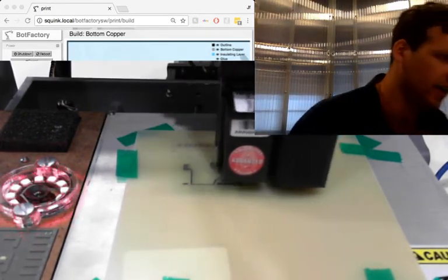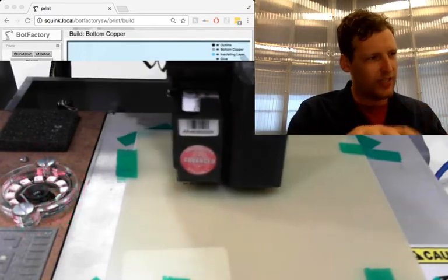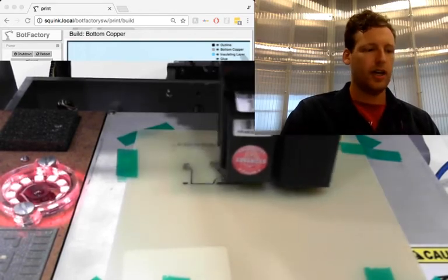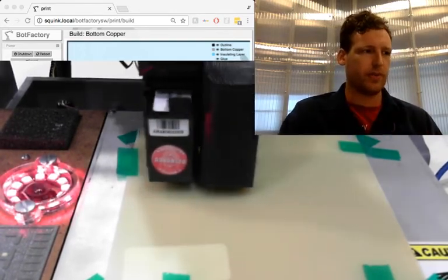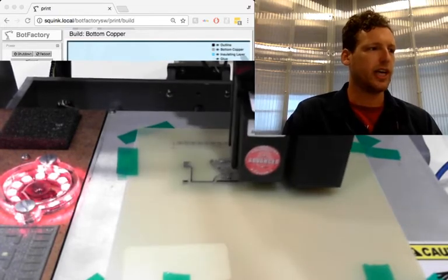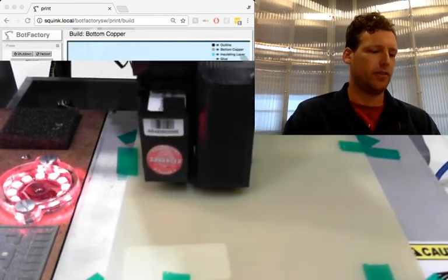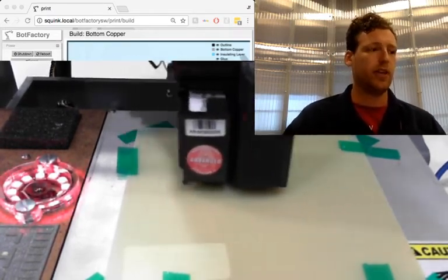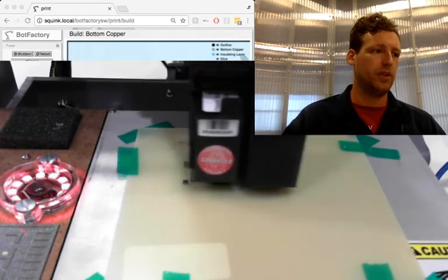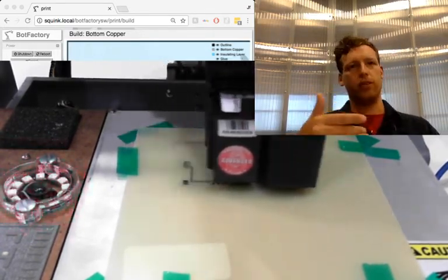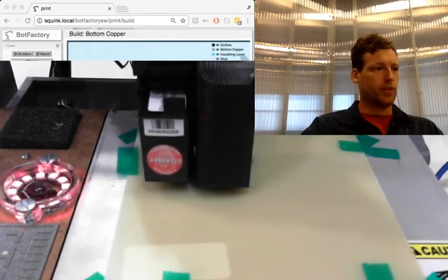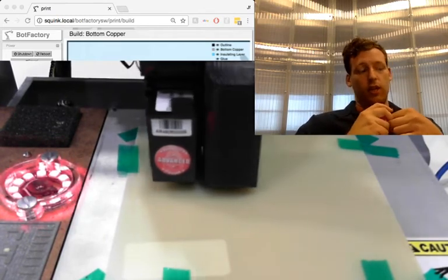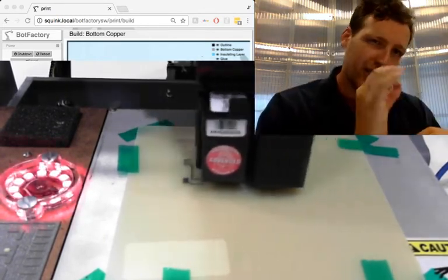You can see the ink is cavitating. When the liquid hits the substrate, it immediately begins to boil away. One of the critical tricks we've been spending a lot of time on is ensuring that the silver remains interconnected with itself. A substantial amount of our research is on strategies for printing. The materials are also another critical element, but you wouldn't believe how much time we spend on the microscope.